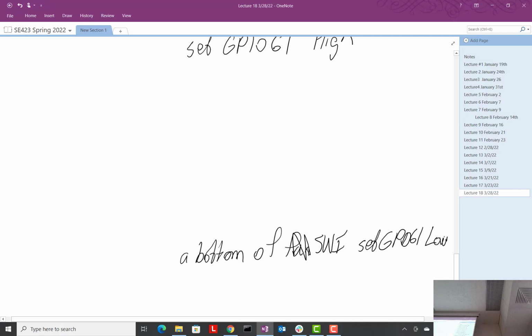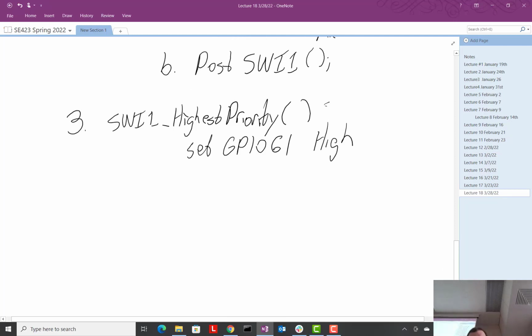Yeah, good. That's what I'm trying to get to. Let's explain that. But that's what we're going to do inside this function. What needs to happen? So that this software interrupt is functioning correctly, it needs to be able to run every millisecond. If you put too much code in there, a post to software interrupt highest priority, another post up there, is not going to cause a second software interrupt to run if the first one hasn't exited.